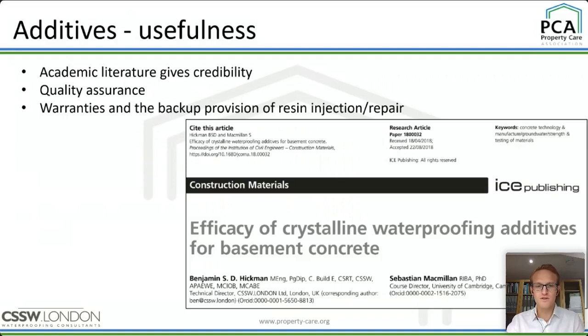I simply looked at what research is available. And there is this thing where the data isn't actually very good. Some of the research that's done on waterproofing additives isn't very helpful because it doesn't allow for the binder change. I won't go into that, but generally speaking, I would support the use of a waterproofing additive, and I think there is good academic literature, particularly for crystallizing waterproofing additives.